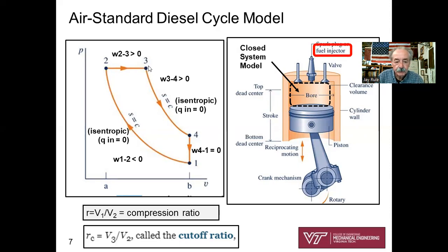All right. Now let's jump to 3 to 4. This is the power stroke. The power stroke, 3 to 4. This is where we're really driving the shaft to produce power to deliver to the wheels, the tires of the car. Isentropic expansion, 3 to 4. Okay, power stroke. And then finally, 4 to 1 in our thermodynamic model, we're saying we're rejecting heat from the air at constant volume. So this completes the cycle. I hope that visually you see, oh yeah, the net work is the area contained within this PV diagram. I think I got it.